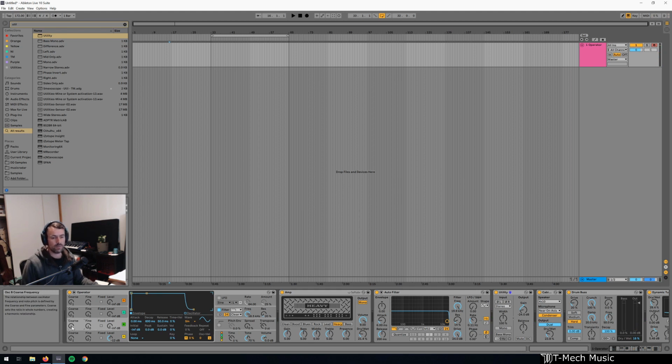What I'm going to do here is wind this coarse value down to 0.5, which is below 1, and then bring the fine all the way up. So it's basically, at this point, it's at 1 again. Then if I bring the fine value down, I'm detuning down from 1. You can hear already we've got the two oscillators beating against each other.